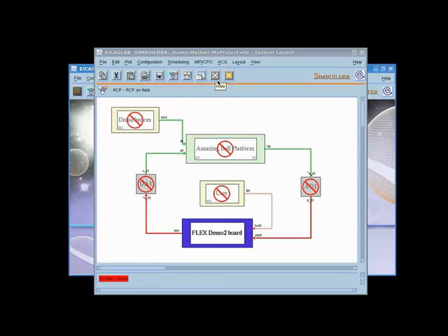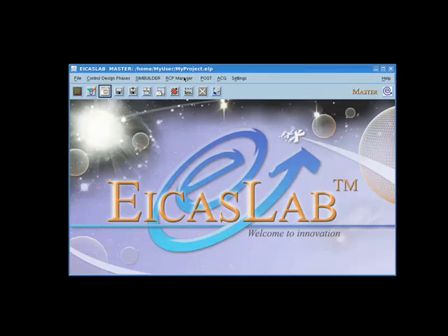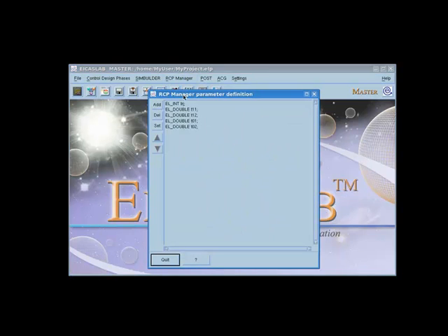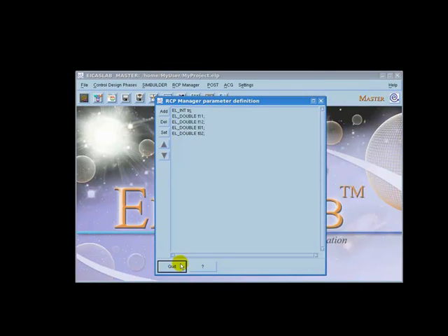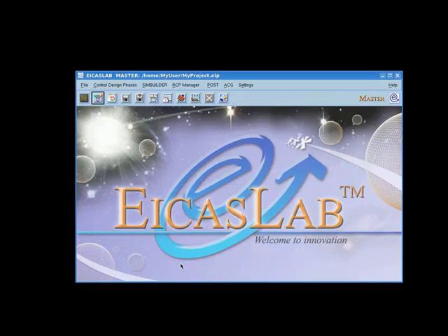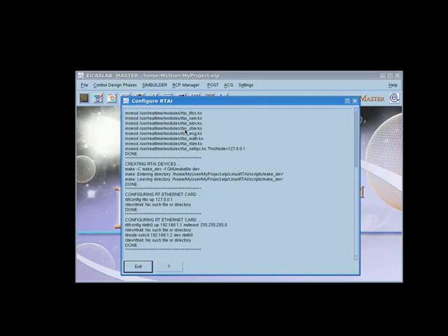When all the interfaces have been set up, through the master tool it is possible to open the RCP Manager parameter window. By means of this window, the user defines a set of parameters that can be changed asynchronously during the trial execution. In this use case, we have inserted the trajectory and its parameters for modifying the trajectory during the real-time execution. Now the system is ready for loading the real-time modules into the Linux kernel.